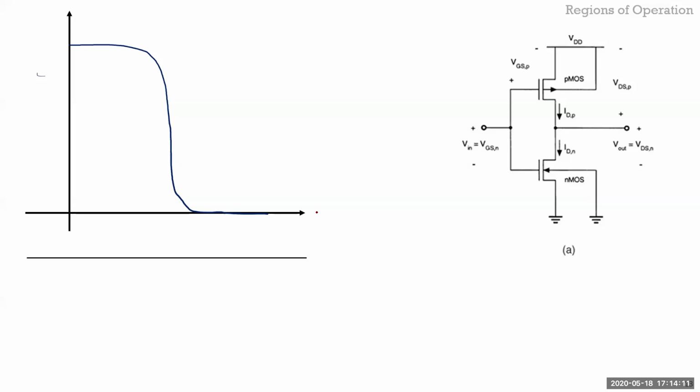Okay, I'm back. Sorry. So in case of the CMOS inverter, like we saw, this is your input voltage, Vin, obviously. This is your Vout. And obviously when the input is 0, only the PMOS is on, so this charges up all the way to VDD, right? And in the opposite case, the NMOS completely discharges to 0 volts.